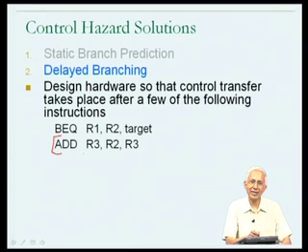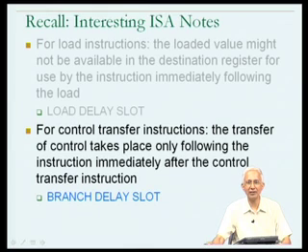Then by doing this, I am actually providing that one cycle in which I need not make a guess about whether the branch instruction is taken or not, because the add instruction has to be executed by definition. And therefore, I avoid the stall cycle entirely. There is no need to make a guess, there is no need to stall the processor for one pipeline. After the conditional branch instruction, we automatically execute the next instruction as per the definition of what a branch instruction means. And we have seen this idea before.